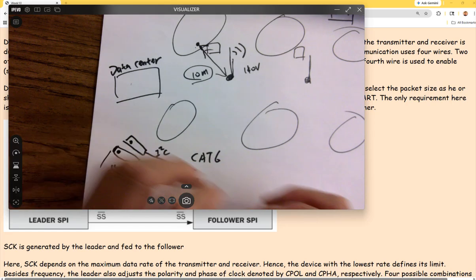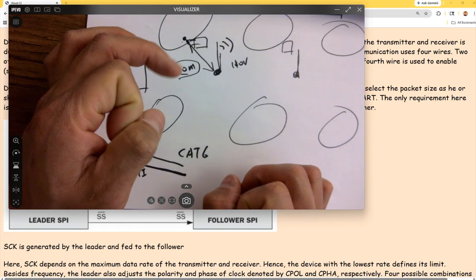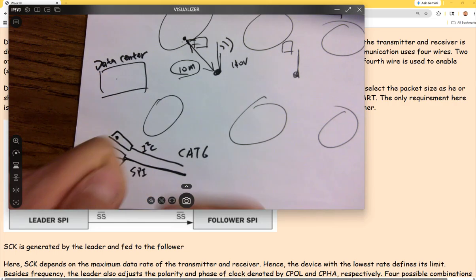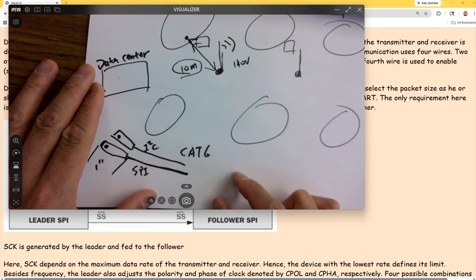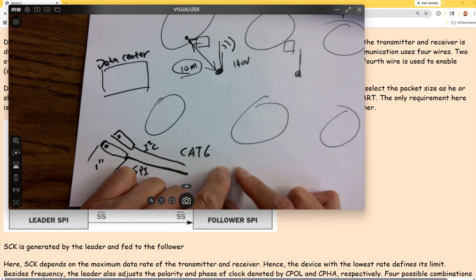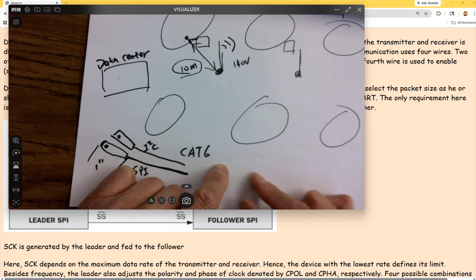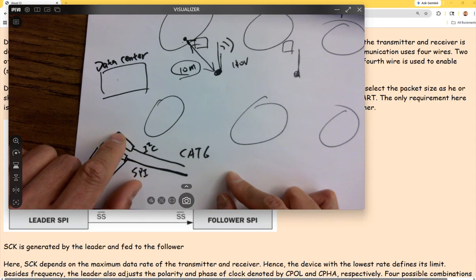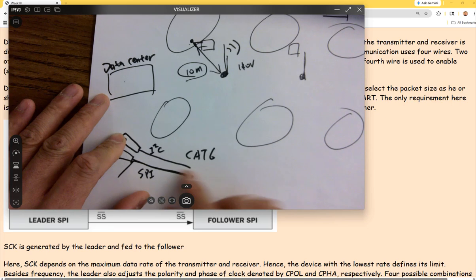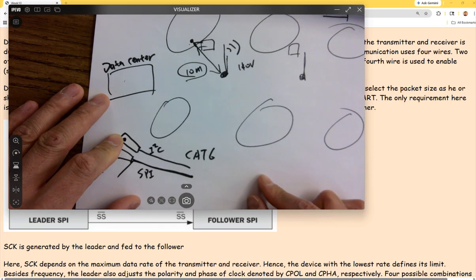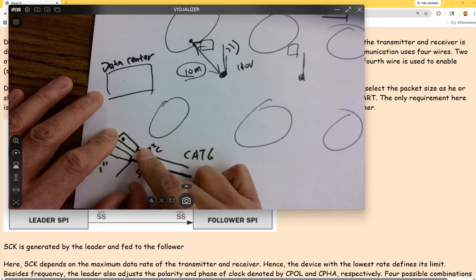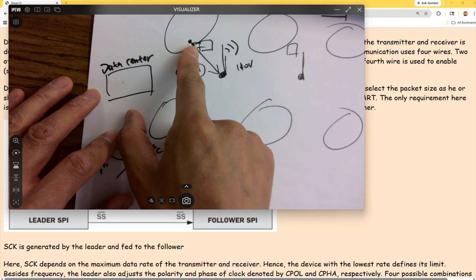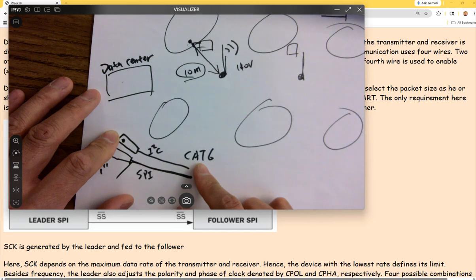And then you buy some of the Ethernet connectors, and you use a certain tool to make the connection from the connector to the cable at the other end of the cable, right? And so you can just plug that terminal into your PCB's female connector, and eventually receive the digital signal from this guy. So that one can run for at least 100 meters. I tested, which is amazing. So for temperature sensor data, if you have to run it through the wire, you have to use a Cat6 internet cable.